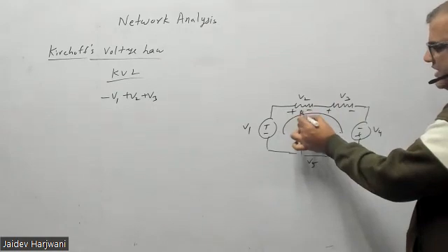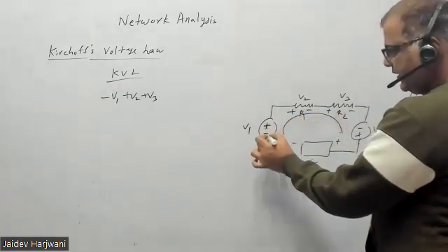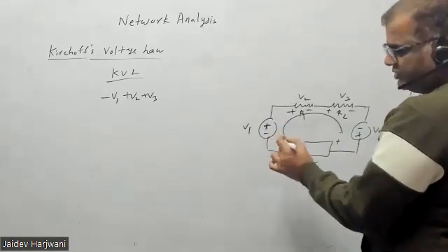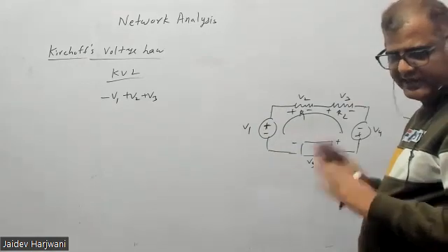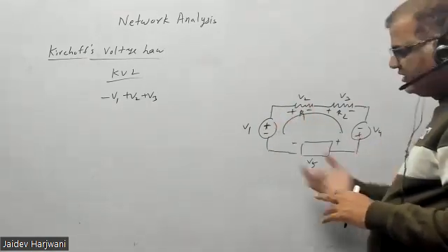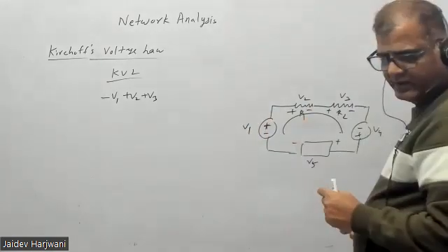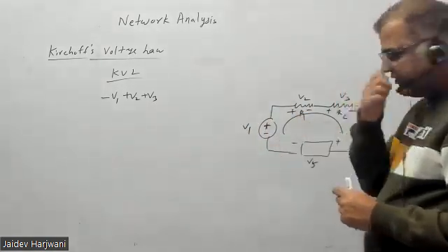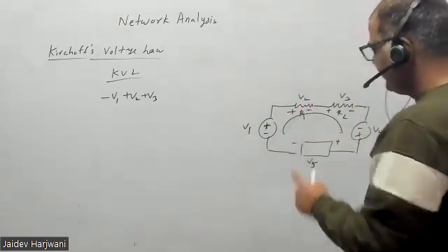Okay, some resistances will be there, say R1, R2. This is the voltage, so this is a voltage rise. I'm noting whether there's a voltage drop or voltage rise. Any voltage or voltage difference, for example from this point to this point, you have to write. You have to move in the loop and put everything with its sign.